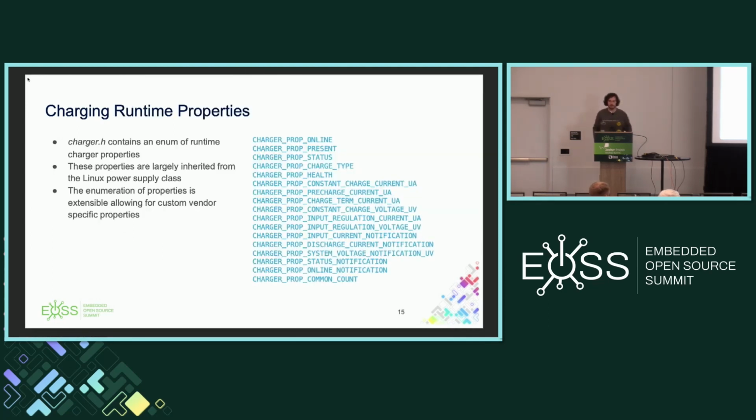So the online notifier was added because there's a Maxim chip, and I've seen this kind of requirement in some other vendors' silicon where using the interrupt line is required, which is not super common in Zephyr. A lot of times the peripherals are just polling, but for that specific chip, you need to use an interrupt line.